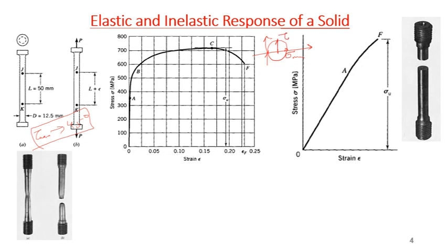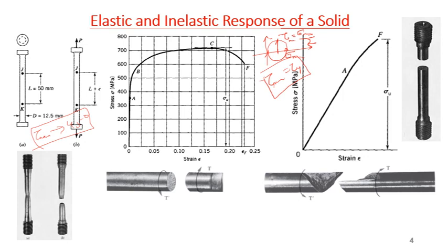And we have maximum shear stress, tau equal to tau max. In this case it will be sigma max by 2. It's very simple, right? So if you have a ductile material, when will it fail? When you have max sigma tau y, it fails under shear. So when tau max reaches tau y, very simple. But that is for the uniaxial case. If you have a torsion load, then what will happen?